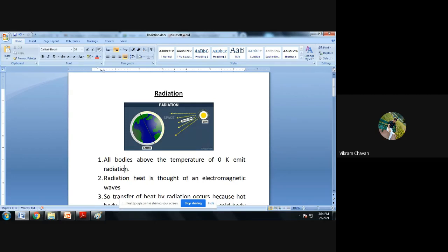We also discussed the dependency of convective heat transfer on fluid properties such as thermodynamic and transport properties, thermal conductivity, specific heat, kinematic viscosity, dynamic viscosity, then fluid flow condition like laminar flow, turbulent flow, transition flow, then the temperature conditions like the temperatures of the surface and the fluid and their difference, then geometric condition, whether the system is a plane wall, a cylinder, or a sphere.